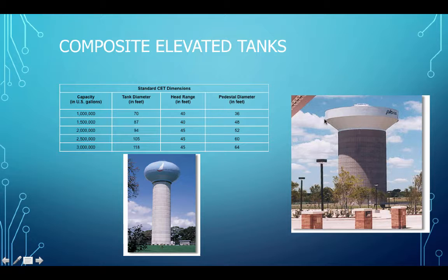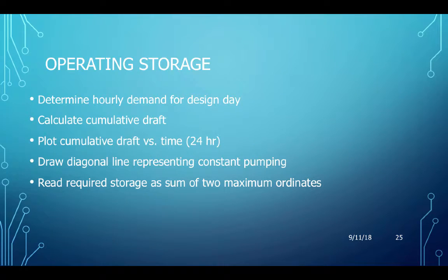So a lot of the storage is in the diameter part, and the head range is fairly narrow, and that sort of makes sense because we're having to hold all that water in the air, and we're going to be structurally limited at some point. And getting it too high, the wind loads are going to be oppressive.